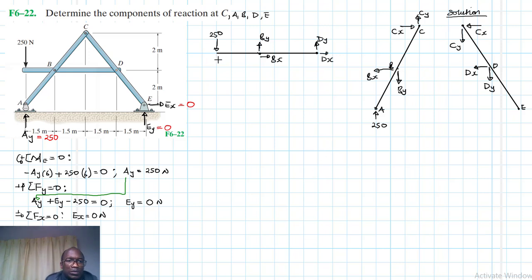Let's start with this member here, BD. Let's apply the equations of equilibrium. So let's say summation of moments about point D equal to 0, and clockwise being our reference.